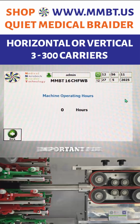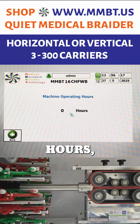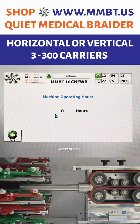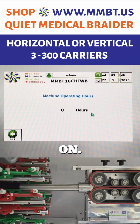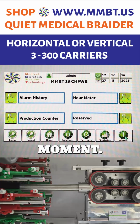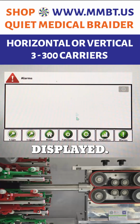Hour meter. This is important for PM on the machine. Every 8 machine hours, we want to pump our grease gun 5 times. This is only for the amount of time the machine actually runs. This is not how long it's powered on. So that's where you find that number. And this is reserved at the moment. Last settings is just any current alarms that are on. This is where they're displayed.